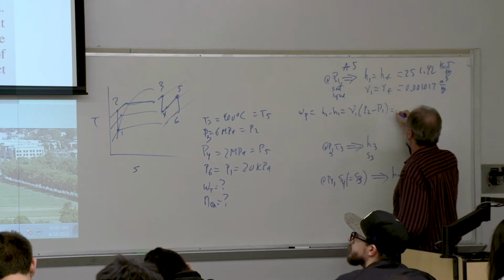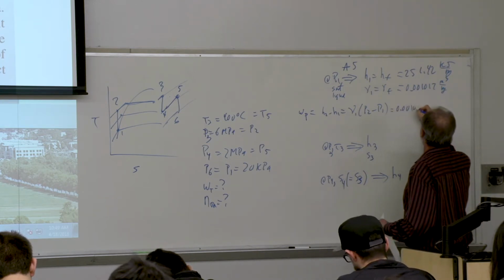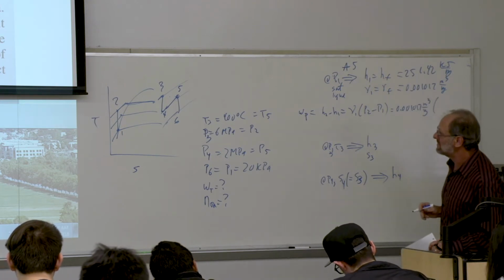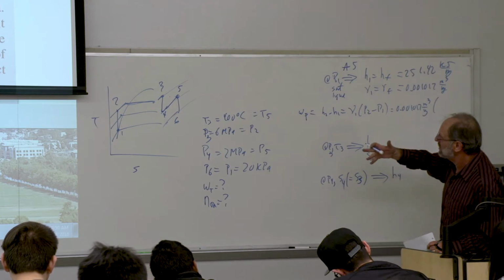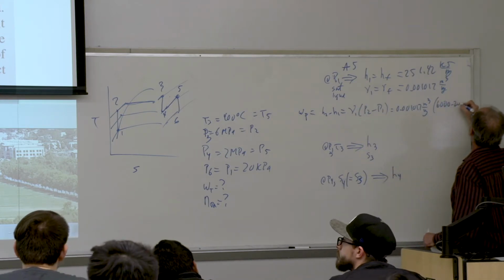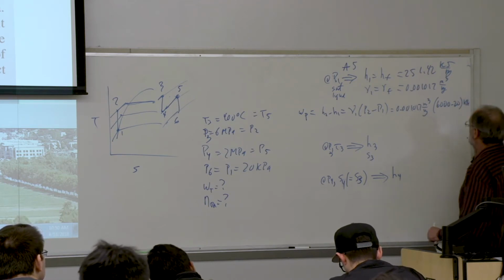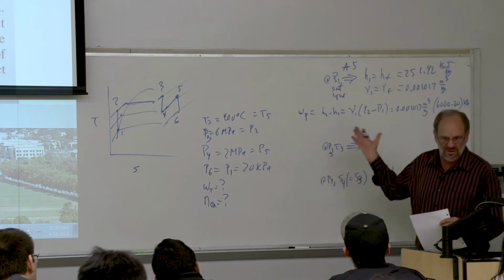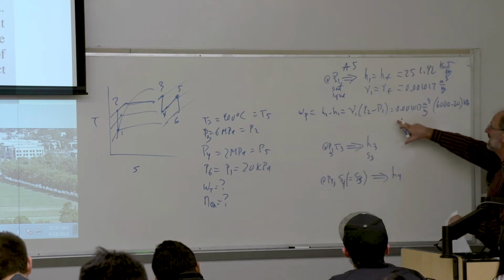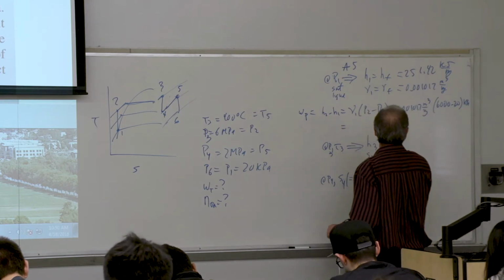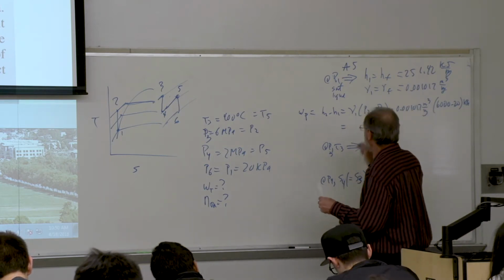We can now plug this in below. And the pressure difference from 1 to 2 is between 20 and 6,000. Certainly we need to make sure everything's in kilopascals. And of course, the kilopascals are kilonewtons per square meter, et cetera. The units cancel. We've seen this before. And this just gets us into kilojoules per kilogram, so no conversion factor is necessary. This is 6.08.